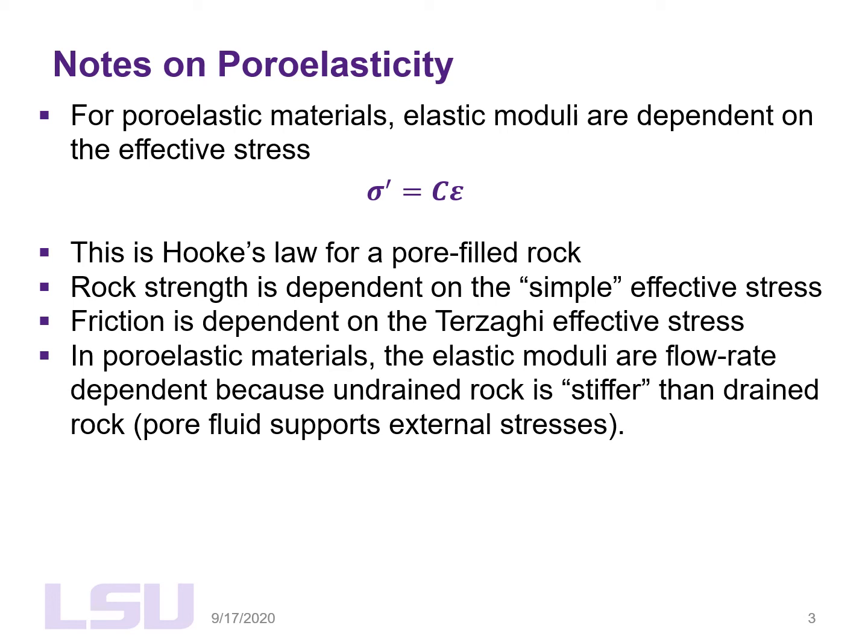Notes on poroelasticity. Yeah, it was total stress for normal materials, but for porous materials filled with fluids, then we use the effective stress and not the total stress, because we partition the total stress into the effective stress and the pore pressure. And this is your Hooke's law for a pore-filled rock.